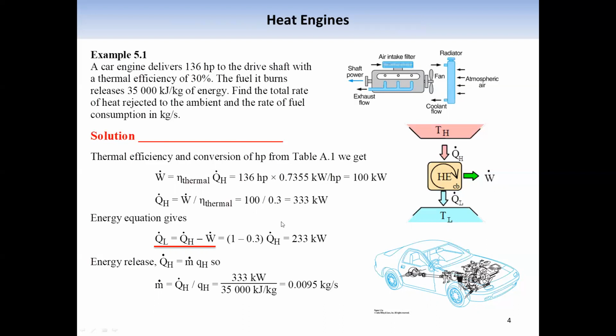And then we use the definition of thermal efficiency. We can estimate the total energy provided by the high temperature reservoir. That's this number divided by 30%. Then we can figure out the QL term.